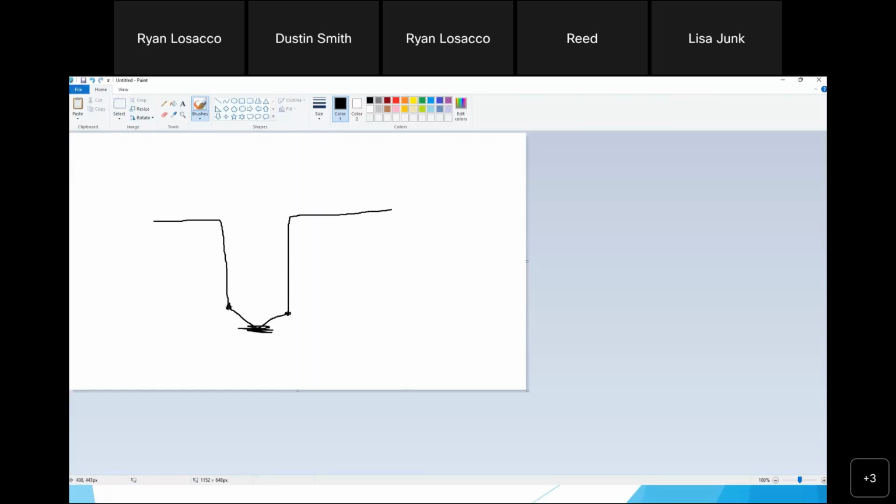So height-wise, we're measuring here, and that's the distance that we're probably going to want right there. We could use a caliper, and if we use a caliper, I always make sure that when I use my caliper, I make sure that little notch at the bottom of my depth rod is away from the sidewall because my caliper will hit at that point right there. So just think about that.